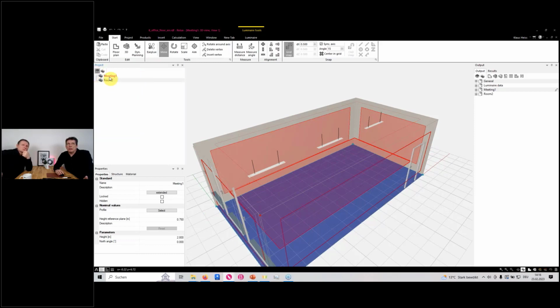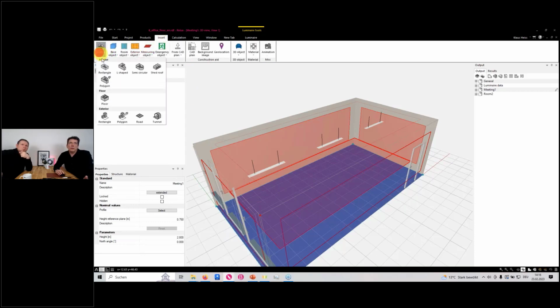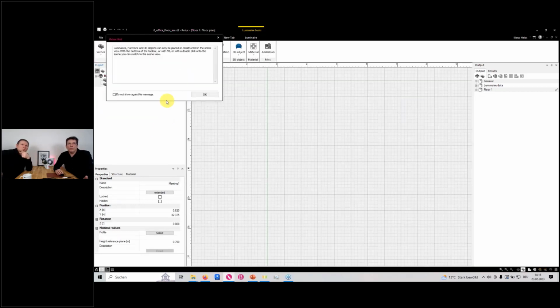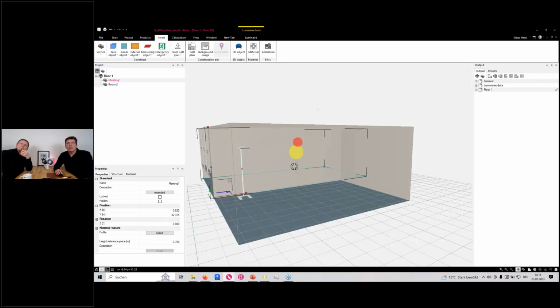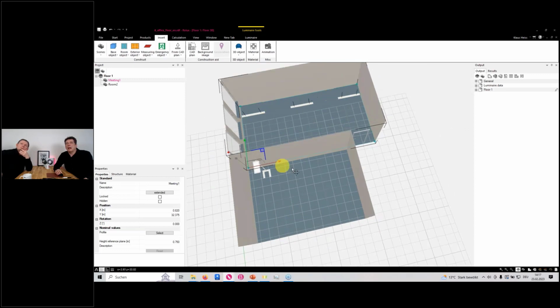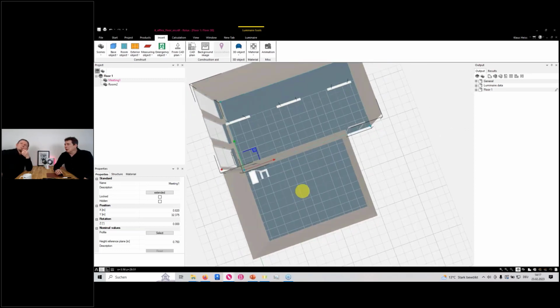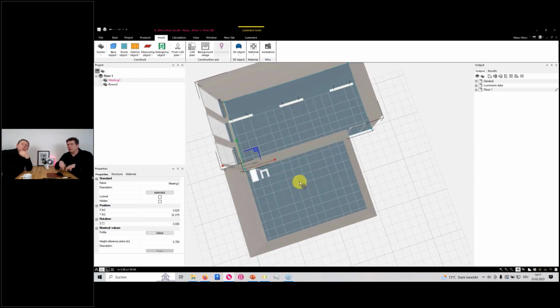Also interesting is that at the moment these 2 rooms are standalone in my scene tree, but I have the possibility to merge them together by entering a floor. And if I take a look at the floor plan, you will see that they are lying correctly, according to where they are in the DWG file.